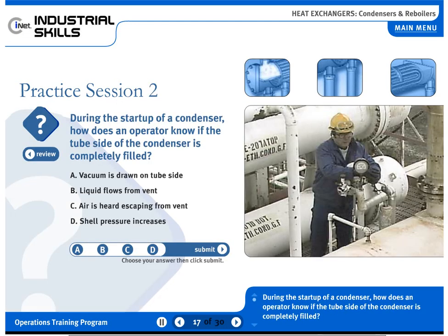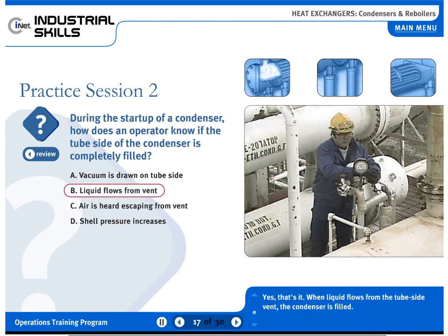During the startup of a condenser, how does an operator know if the tube side of the condenser is completely filled? Yes, that's it. When liquid flows from the tube side vent, the condenser is filled.